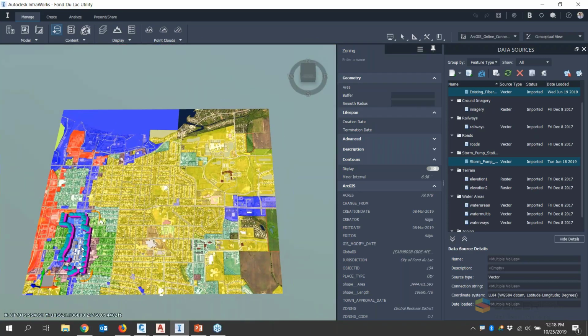And then once they're done here, I have two options from Infraworks. I can either open this up in Civil 3D and bring those surface data and items in, or actually, because Infraworks is a SQLite file, back when we started there in Map 3D, I can connect to this map in Map 3D. I can make an FDO connection to the SQLite file and bring all this layer data in and make any kind of maps that I want to in there as well.